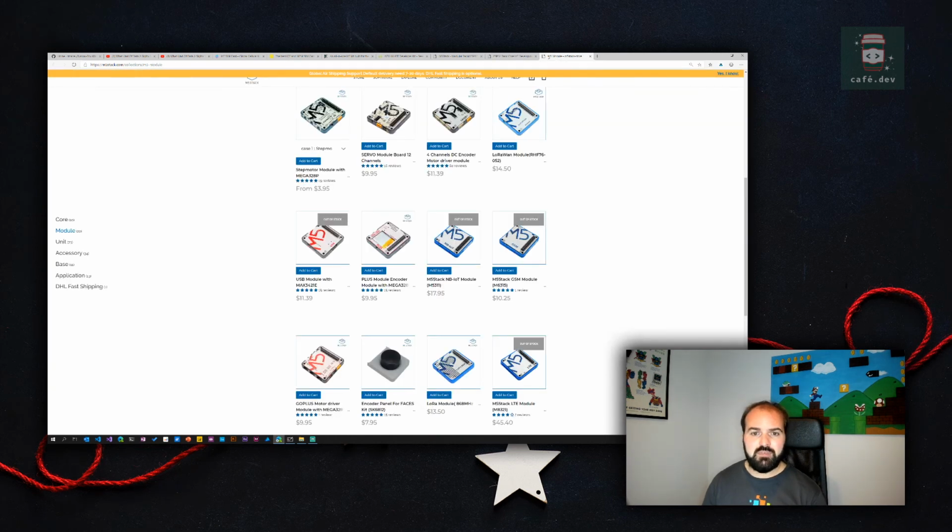Fortunately, as the M5 Stack is composed of a lot of modules you can buy and just clip on the basic core kit, they have some GSM, NB-IoT, and LTE modules. I will just have to buy one of these modules and stack it onto the M5 Stack, and then I will have a fully autonomous device with battery inside, with a screen, with internet connectivity, with buttons. So with this, I will fit all the bill I have for this project.